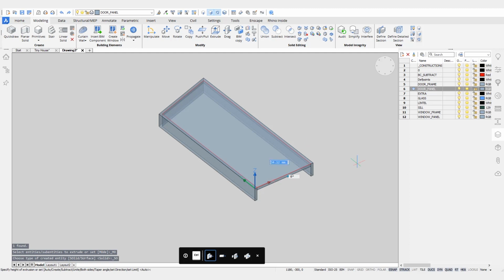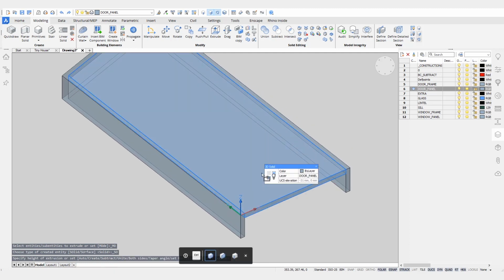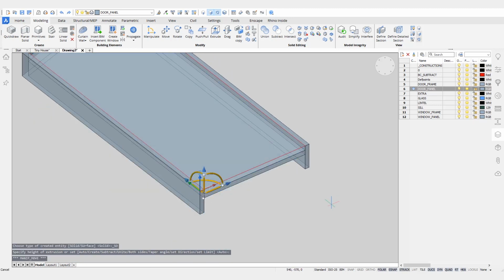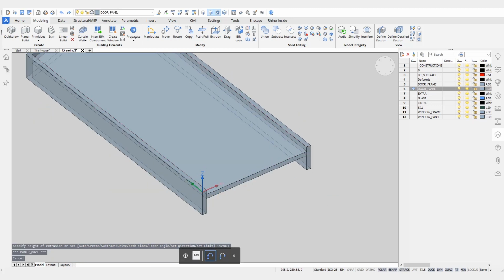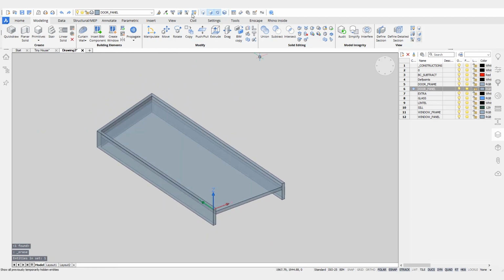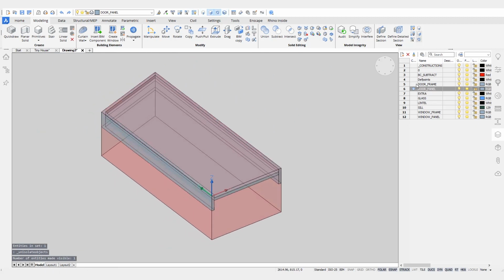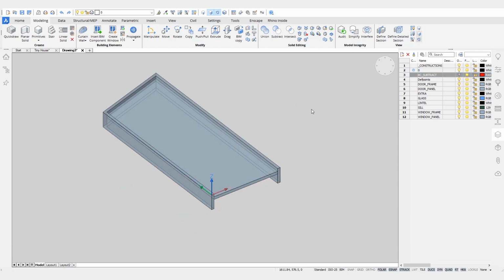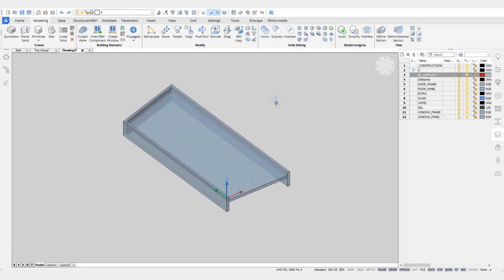When we insert a door, once we hover over the correct face, it will flip the correct side up because we dynamically change our UCS according to the face where our cursor is placed. If I would place my cursor here, you'll see the door flip like this. So that's why I'm creating my door lying face down.